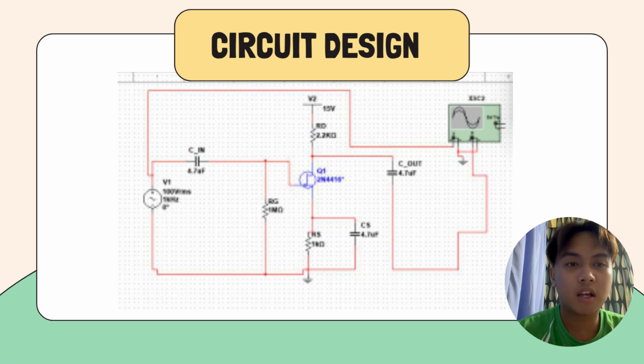I included coupling capacitors at the input and output to block DC voltages from interfering with our signal sources or the load. I also added a bypass capacitor CS across the source resistor, which is so important for the AC analysis because it shorts the source resistor to ground for AC signals, which maximizes our voltage gain.